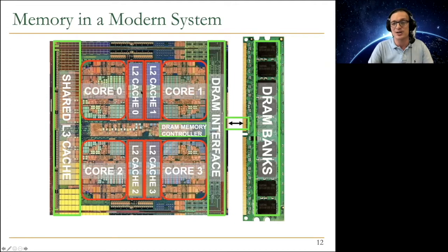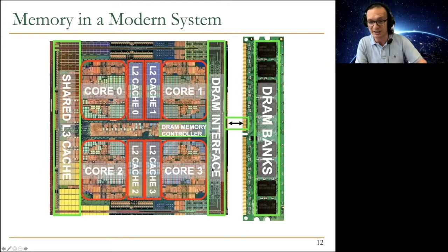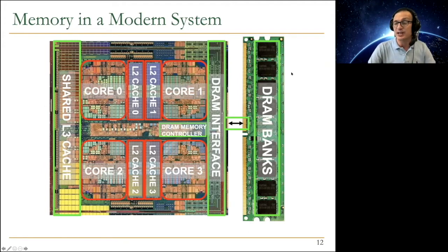But outside the cores, you have caches, interconnect, other caches, other interconnect, memory controllers, memory interface to do the analog to digital conversion and digital to analog conversion, and to control the memory as well. Other interconnect and memory. As you can see, this is the off-chip memory over here. So you have a lot of on-chip memory, and a lot of off-chip memory as well. And I'm not even depicting the storage units, which is really part of memory as well. So basically, if you look at a system today, most of the real estate is dedicated to memory. And that shows you how important it is, right?